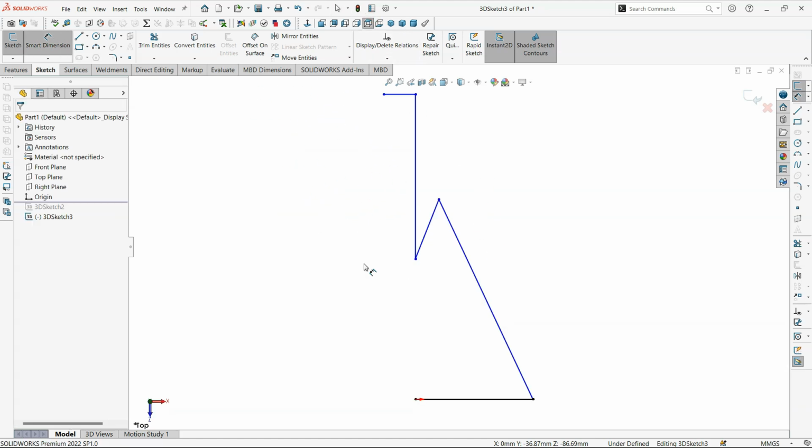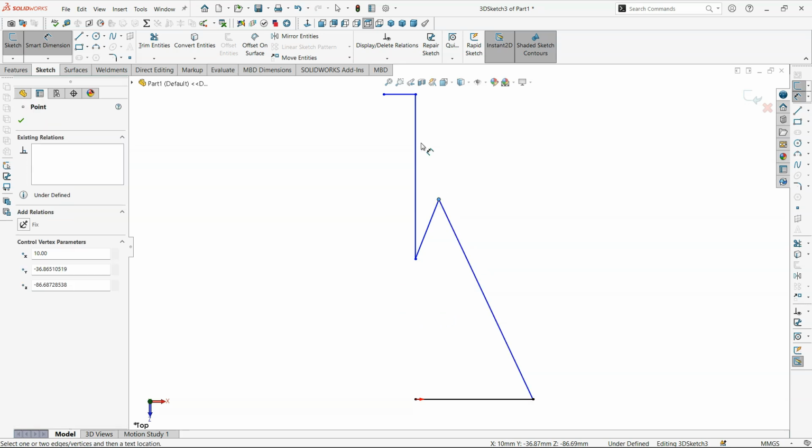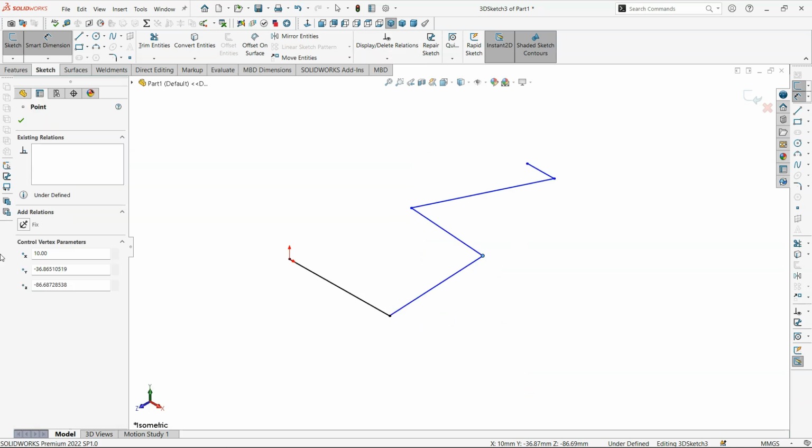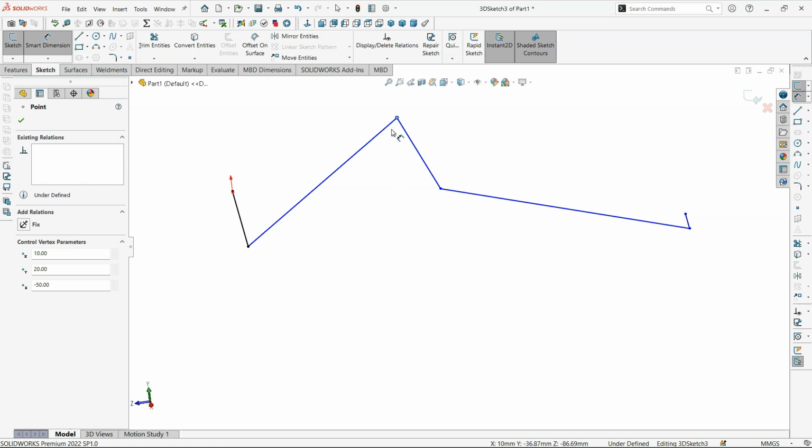You see by going to top plane, you will see how x moves. That's how x currently is in this place. We want y also, inverting it to be positive here. So let me just select 20. Now it is at 20, and z, let's say 50. So you see it is now in a diagonal shape.